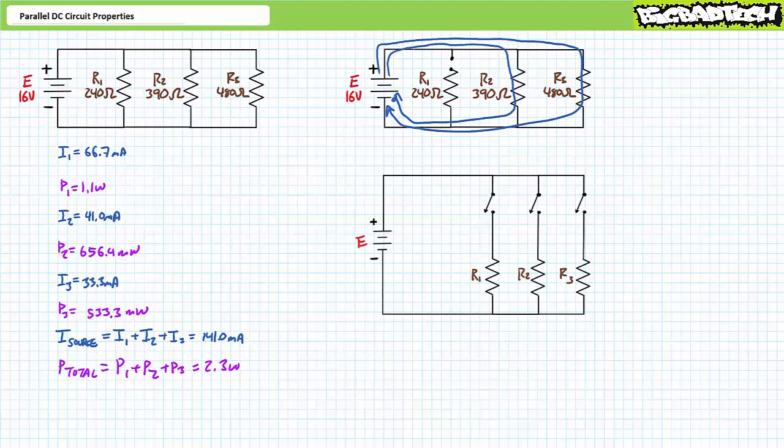This is perhaps one of the best features about parallel circuits. By selectively opening and closing the path to one element, that element and that element alone is selectively energized and de-energized, and in no way, shape, or form affects the operation of other elements in this system. If R1, R2, and R3 represented electrical loads in 3 separate rooms, one could turn on or off loads in specific rooms by placing a switch inside each branch circuit.